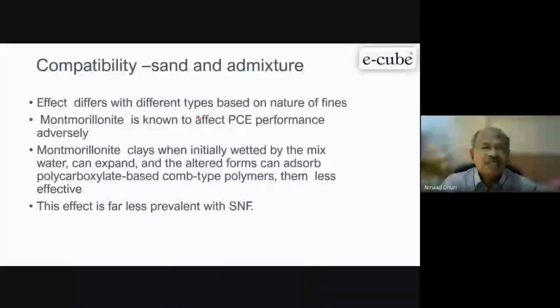Okay, this was what we discussed. That Marsh cone video I'll show you in the next presentation, before we go for fresh properties of concrete. I'll definitely show you that video, how to check the compatibility of your admixture with the particular source of cement. That is a simple test which we can perform at project sites. Whenever a new lot comes, we have an earlier sample and a new sample, we check the performance and accept the material. So within an hour we will know this, and then only we can proceed.